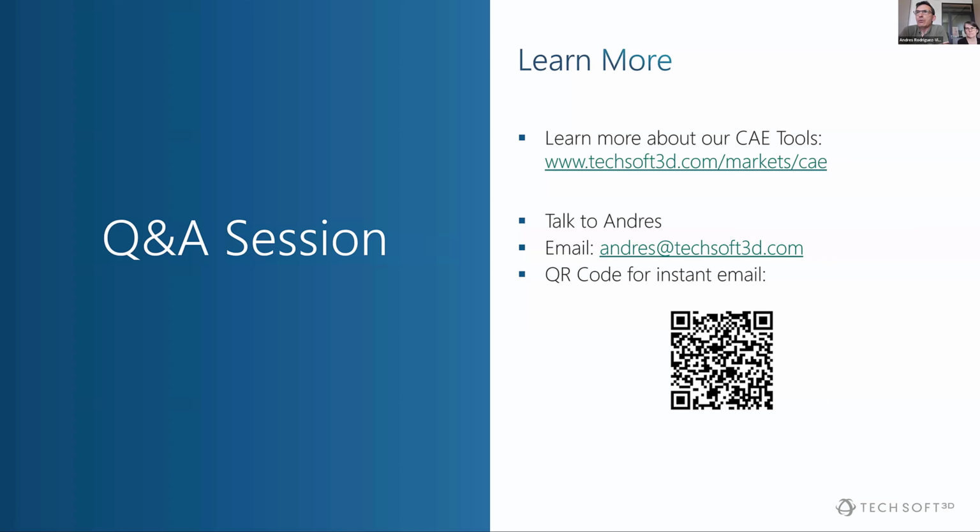Yeah, thank you for that question. I was a bit cryptic while describing the requirements for a mesher. Of course, non-manifold geometry can be converted into many manifold geometries, and there is an option for that in CEETRON Mesh. You have to toggle it on. You also have options for CEETRON Mesh to detect automatically the internal surfaces and create back-to-back triangles. So both sides of the volume can be fed to the volume mesher. So the answer is yes, basically.